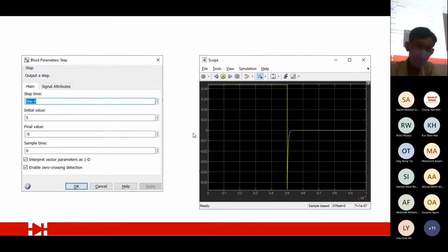Okay, see, this is forward bias, right? It's on, and the moment you turn off, you see it go all the way to negative, all the way to negative. And then only it slowly goes up and then settles at 0. This is the current. So that means this is what we call a reverse recovery.